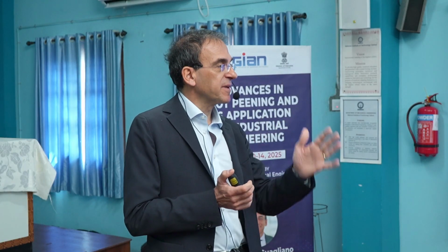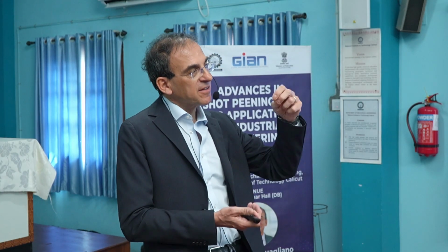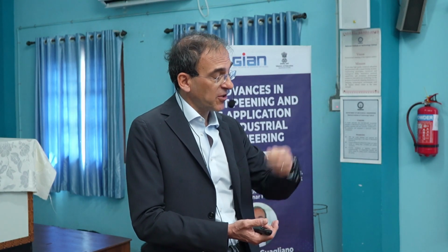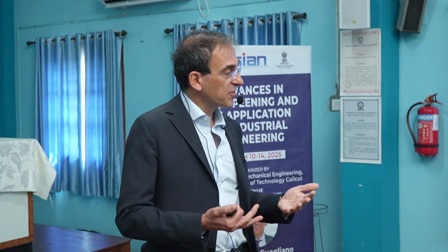Indeed, it is the inclination of the nozzle with respect to the surface to be treated. Generally it is close to 90 degrees, perpendicular, but small deviations from 90 degrees are also usual. Otherwise, the risk is that the peening flow is disturbed. There is an interaction between the incident flow of shot and the ones that are coming back, so that we lose a part of the impact because they are impacting the previous shot that have already impacted.